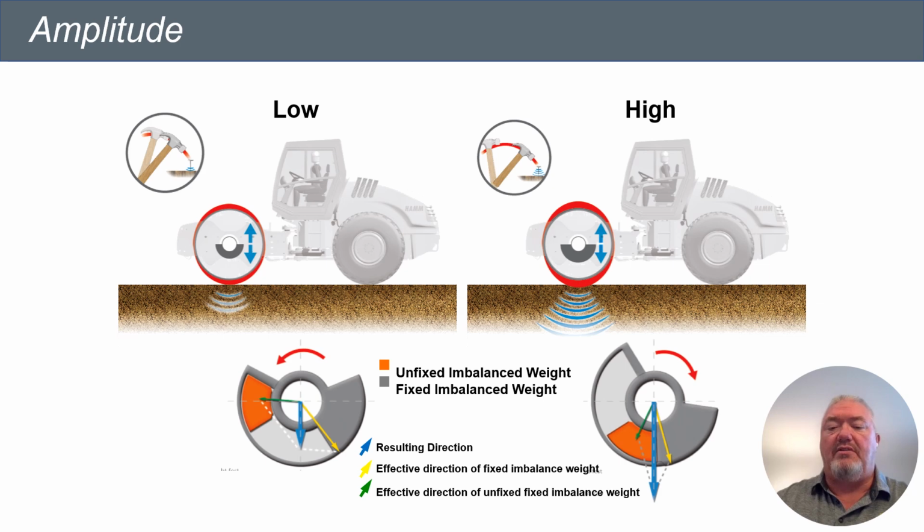If I rotate it the other direction, the weight slides down to where the stationary weight is, and I have a heavier hammer swinging around that axle. With a heavier hammer, I can't swing it as fast, so my frequency, or my speed, is going to be less. But I have a much heavier, or higher, amplitude there.